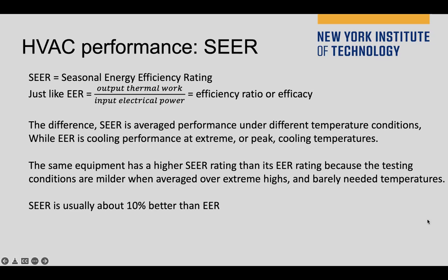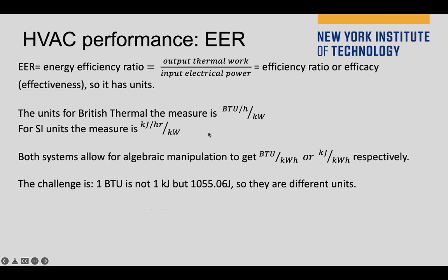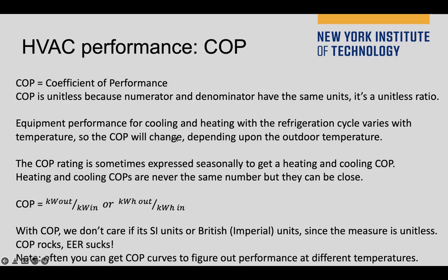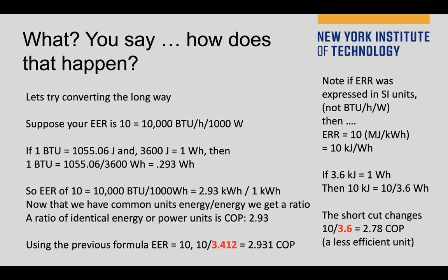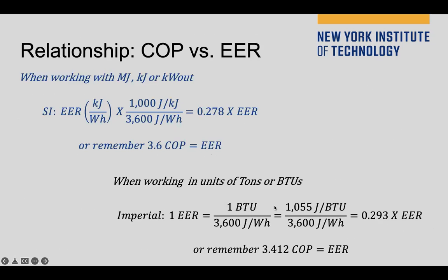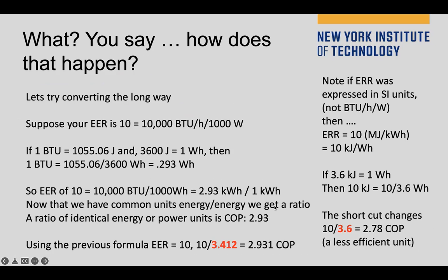EER is efficiency, performance, okay? And the difference between EER and COP is the unit difference, okay? So if you can handle COP, EER, SEER, or just COP and EER, I believe you can handle most of the questions in this HVAC, okay? So let's see some of them. That is also an example to show you how the convention works, by sentence, every sentence to explain this equation. It's more clear and detailed on this.